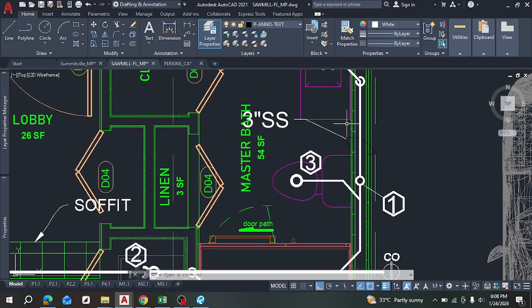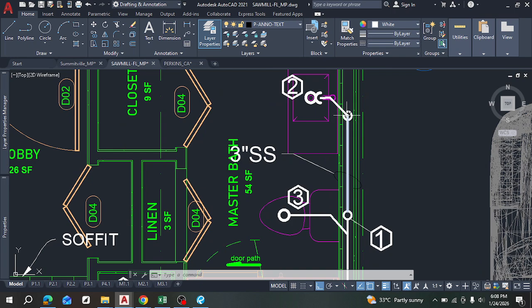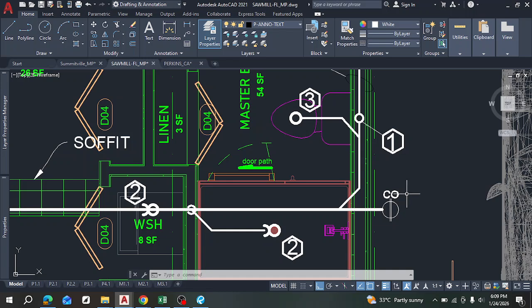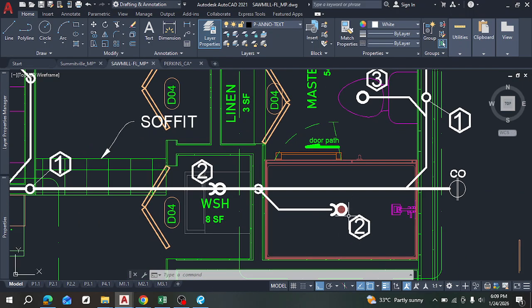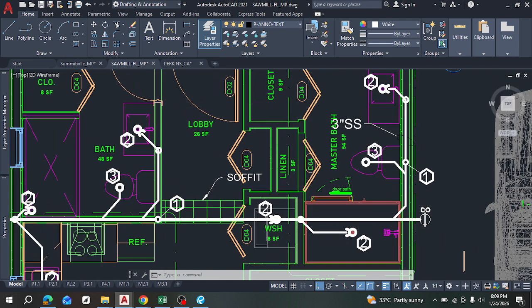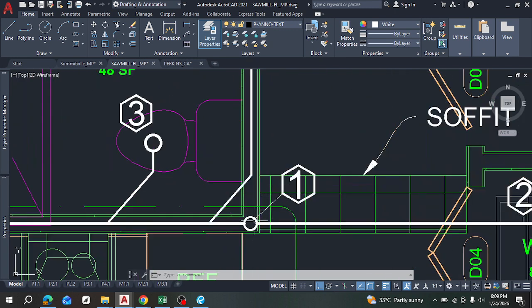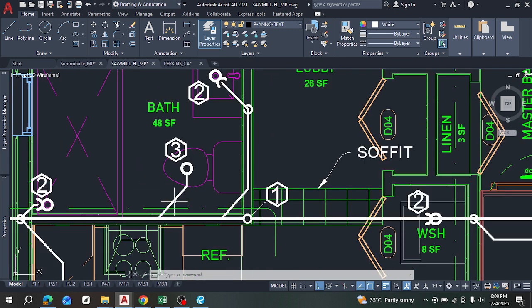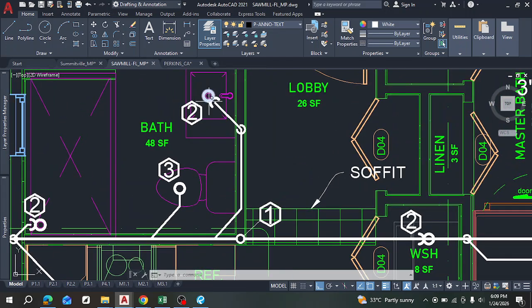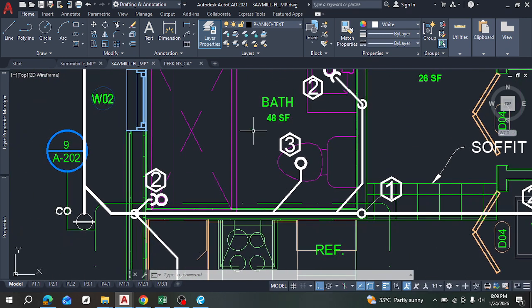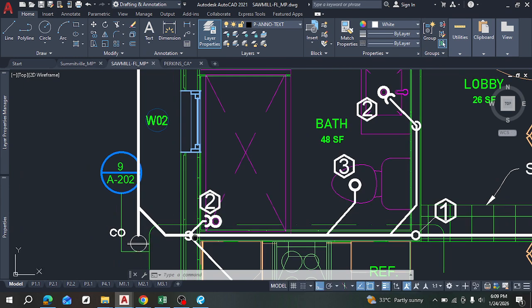the open air, right? This one doesn't penetrate the roof, it's just up within the wall, and then it connects to this one, right? And then this is our cut clean out, and this is another strainer. And if you notice, there's always this size 2, which I've explained before, but we'll look at it again, right? This one is basically another point where it hits, and if you notice, all these are usually along the walls, right? That is why it's necessary to extend your pipe into the wall, so that it's easier to vent, right? And then this is another clean out.